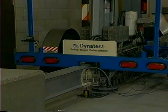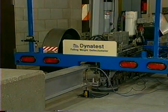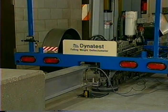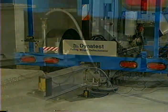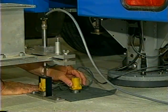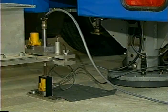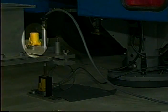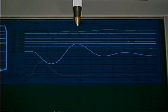So, the system is also designed to delay the deflection impulse from reaching the beam until the deflection has already been measured by the LVDT and the sensor being calibrated. To be sure there has been a delay, a second sensor is placed here at the end of the beam. Then you compare the timing between the second sensor and the sensor being calibrated. You can see the time delay on your computer.